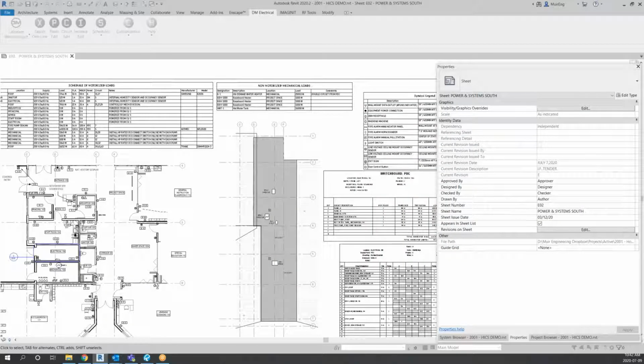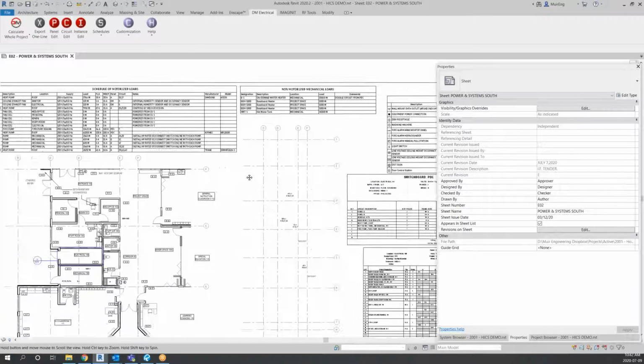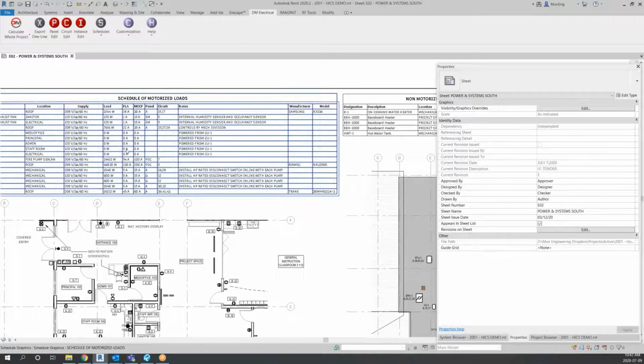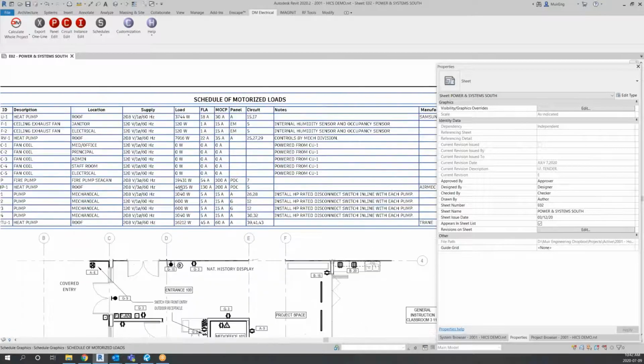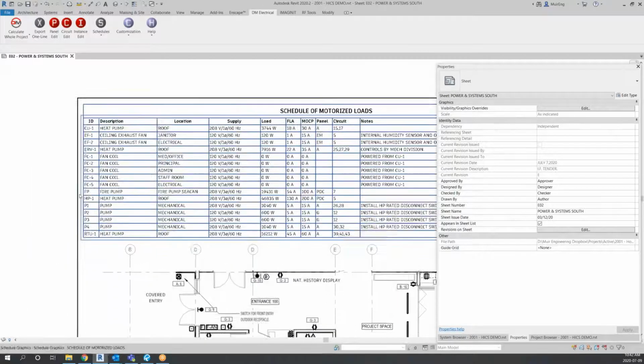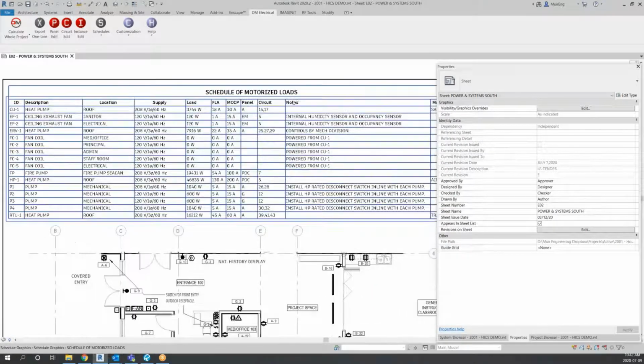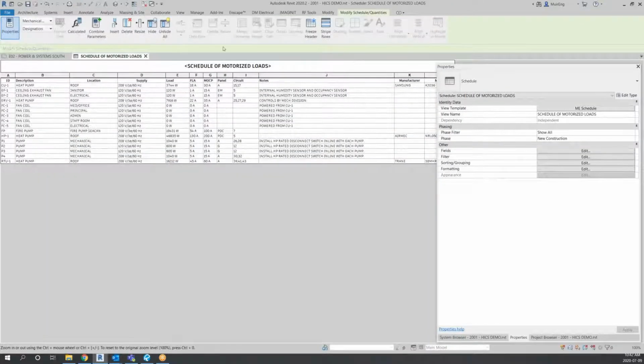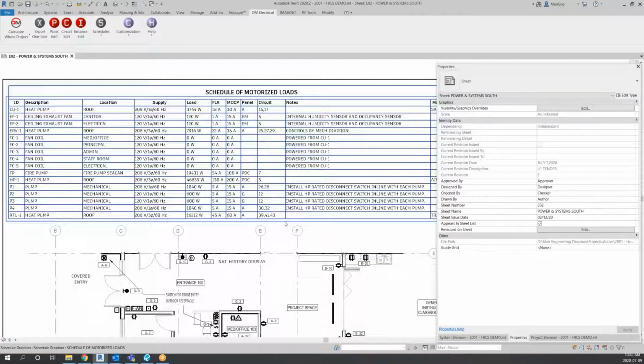Okay, I'll move on. There's a follow-up question that did answer his wire sizing question, and then he wants to know where does that show up on the plans? So I guess where are you showing it in particular? Okay, we often don't show it because we call for wire size to the breaker and not reduce for mechanical loads. However, for this big heat pump, we might actually want to reduce it. So we could add a field to this schedule to show wire size as a call out from Design Master.